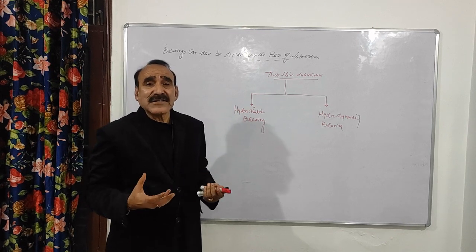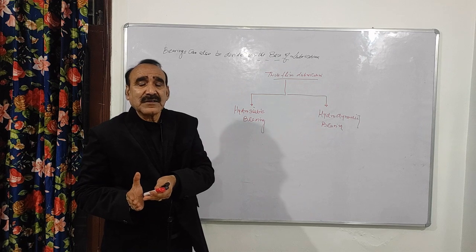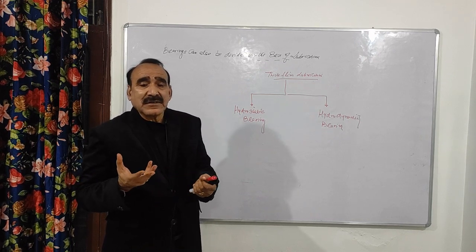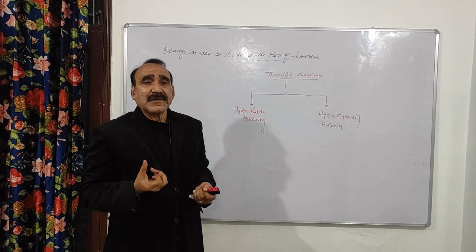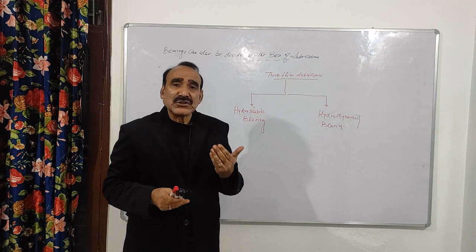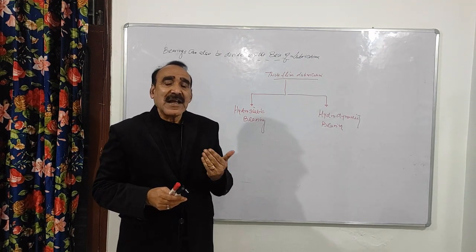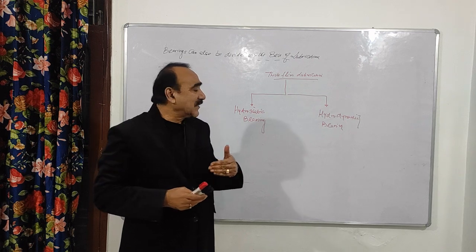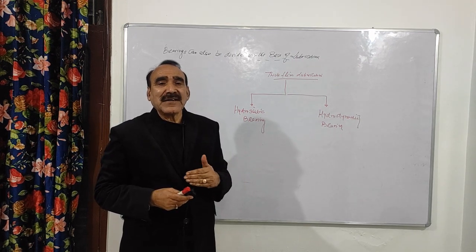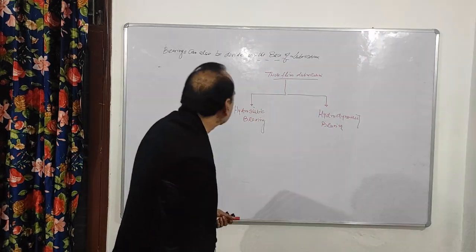One by one we will discuss what is your initial stage, then how the load of the shaft is taken up. Second one is when it is initially starting, when it doesn't attain the maximum position, at that time what is the condition of the lubrication, and the third one is when it is running at the full speed, right? So I will discuss one by one.